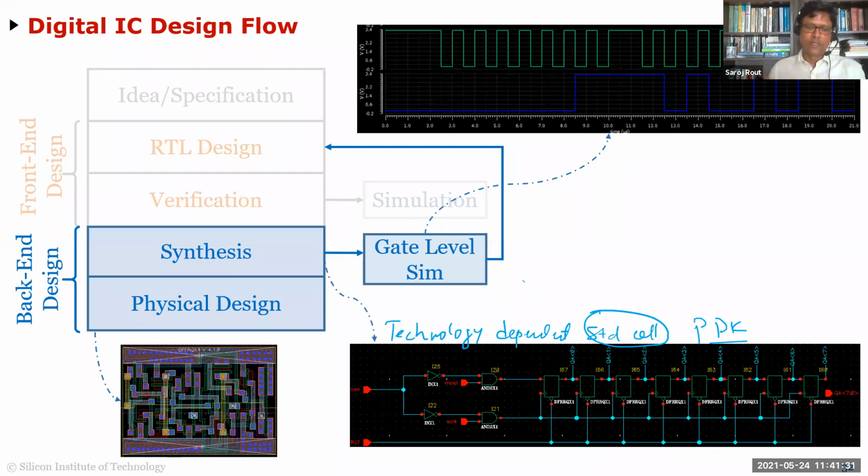Now, in full custom flow, like the chip we designed here, for example, in silicon, we did SRAM with decoders and all that, with a SPI and all that. That was actually a full custom digital design, in the sense that we used standard cells, but all the routings and placements and all that was done by hand. It was a small design, and it was for undergraduate students like you, and I wanted them to get a full custom experience. So we did that whole thing. The whole thing was actually laid out by hand. There was no automated tool use.